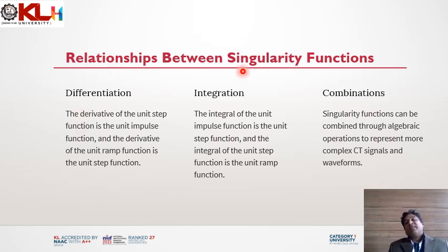Now here we are again just giving a summary of the singularity functions. Differentiation: the derivative of the unit step is the impulse function and the derivative of the ramp is the step function. Similarly, now we will see the integration. The integral of the impulse is the unit step and the integral of the unit step is the ramp. Combinations: we can combine these singularity functions to generate more complex waveforms.